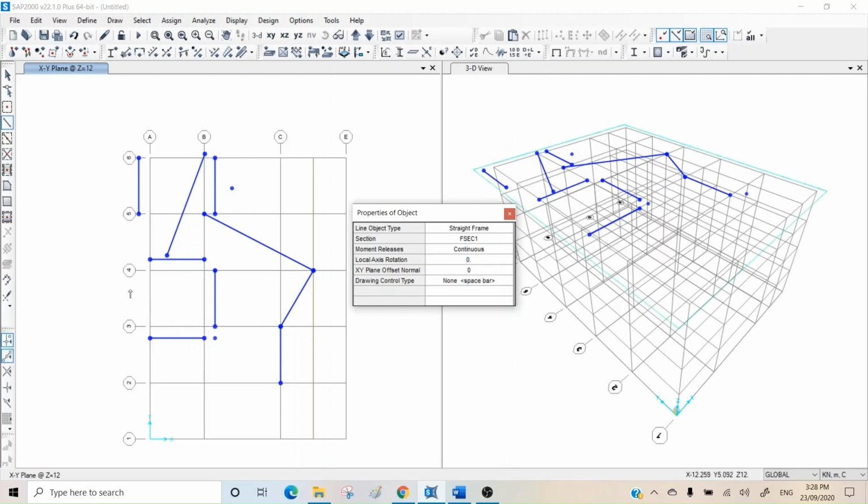And then if I want to draw another element, you can see, for example, a midpoint here to midpoint here, I can draw. The other feature you have here is perpendicular. When you use perpendicular, it cannot be picked at the beginning, it is always the second option.